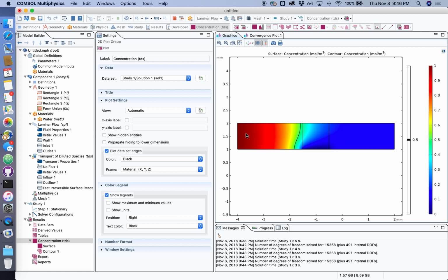The downside of this is that we have such a slow flow at this point that the actual flux of molecules on this sensor, the number of molecules that we're capturing per unit time, is actually really low in this case. And having a higher flow rate might actually be advantageous if the flux is important. If the number of molecules per unit time being captured is crucial, then some of the earlier flow rates that you saw might be better. But at any rate, we've demonstrated here that by changing the flow rate, we pass a waypoint, a tipping point, past which we're no longer depleting just a region of the channel contents, we're now depleting the entire channel contents.